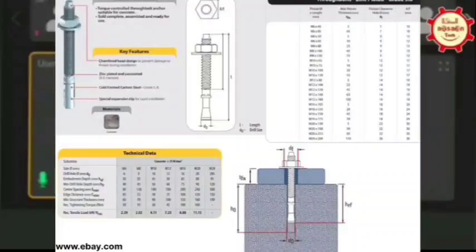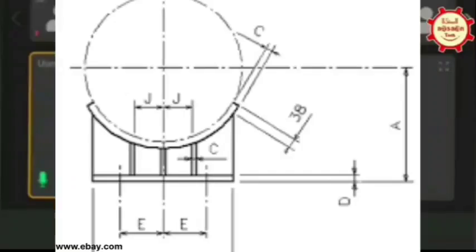Anybody want to answer? No, I didn't get the question clearly. Can you say it again? Yeah, when we design a saddle for a heat exchanger, we have to provide the anchor bolt geometry: what is the diameter, what is the edge to edge distance. And it fails in the anchor bolt check in the report. When we put the shear moment, shear load and wind shear into the manual calculation, it passes with a low bolt size.